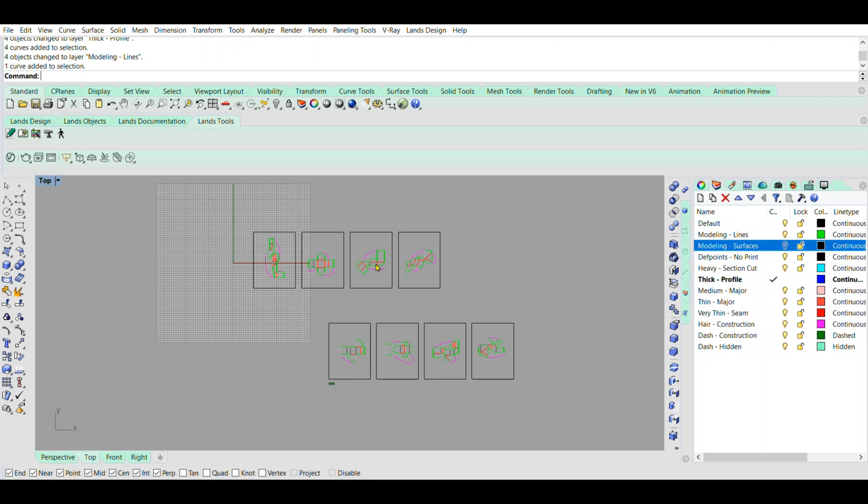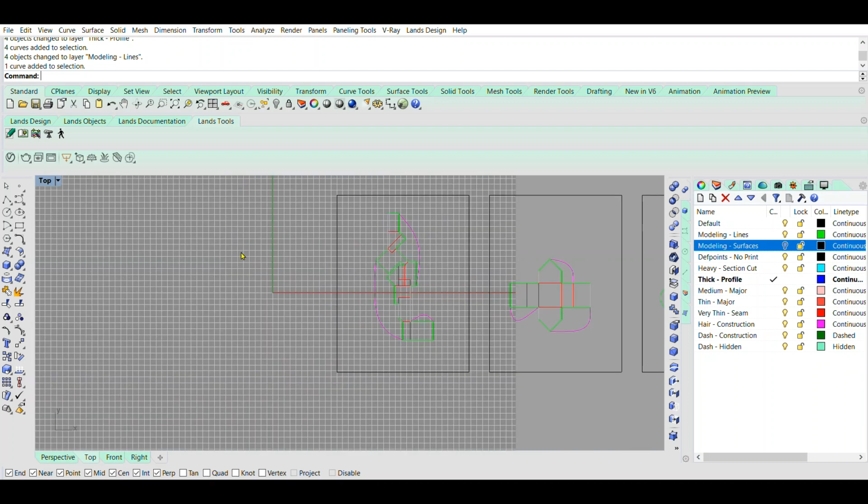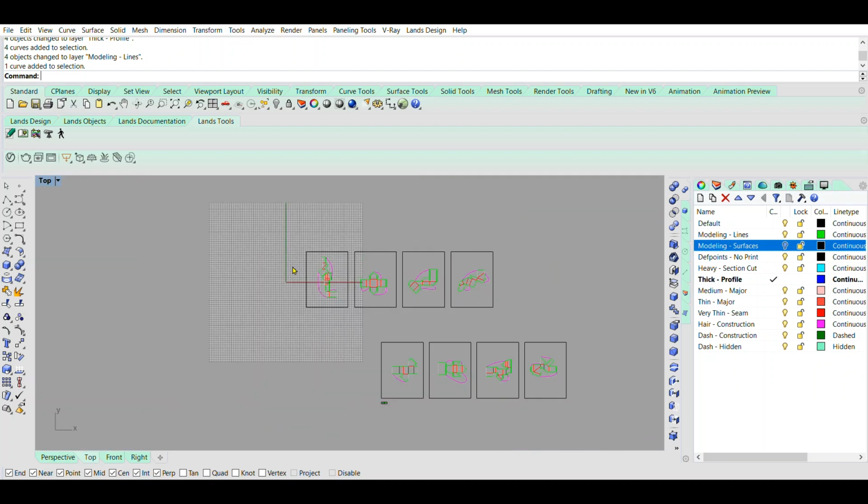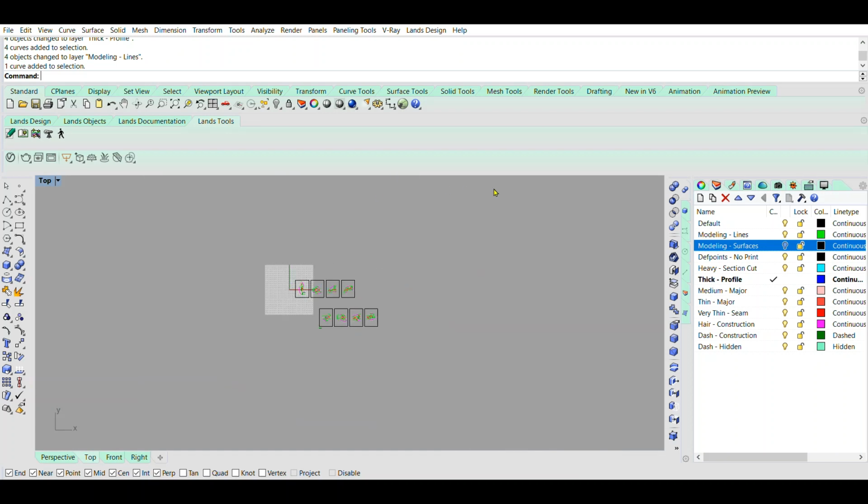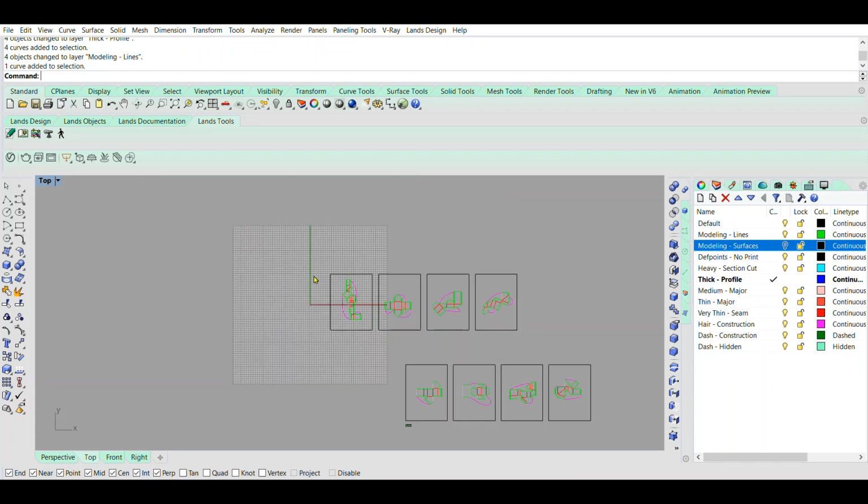And whenever you're exporting from Rhino, make sure the line work you're trying to export is close to the origin. That way, whenever you place it in Illustrator, it's not way off your artboard. And then, like I said earlier, just double check your units in Rhino and in Illustrator and make sure those match, and the scale of that as well.